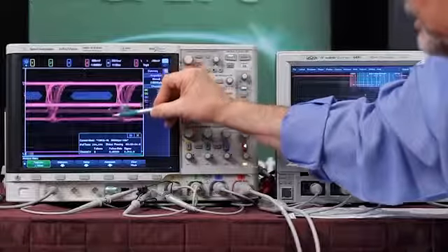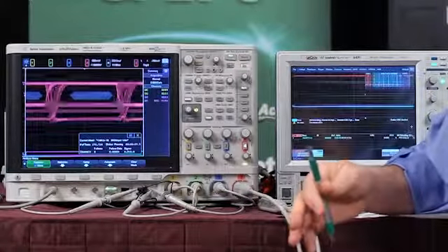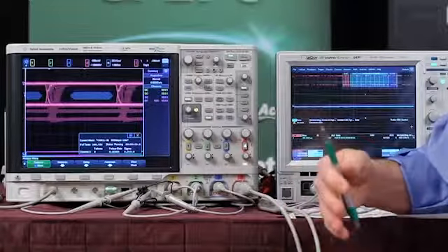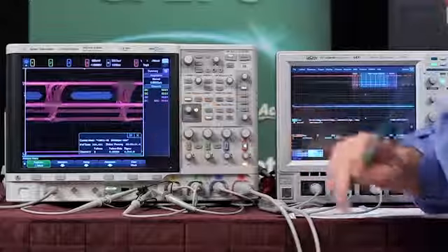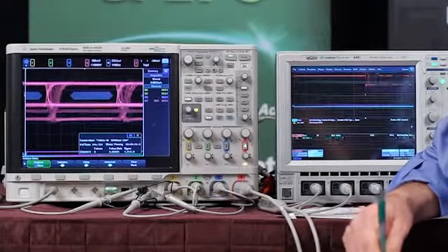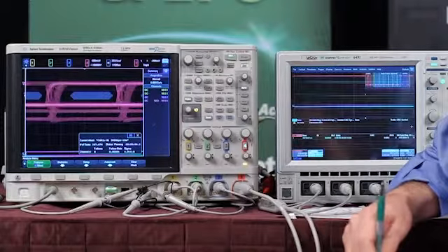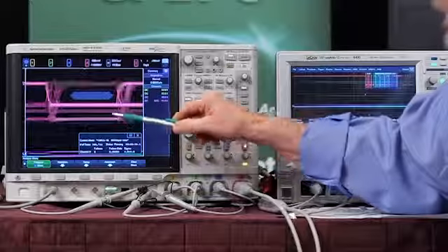It shows you the various amplitude of pulses, which is a result of nodes being separated by distance and different terminations. You can have different amplitudes. Plus, every time there's an acknowledgement pulse, it gets pulled to a much lower level when all nodes pull on the bus simultaneously. And also during arbitration, the same thing happens.